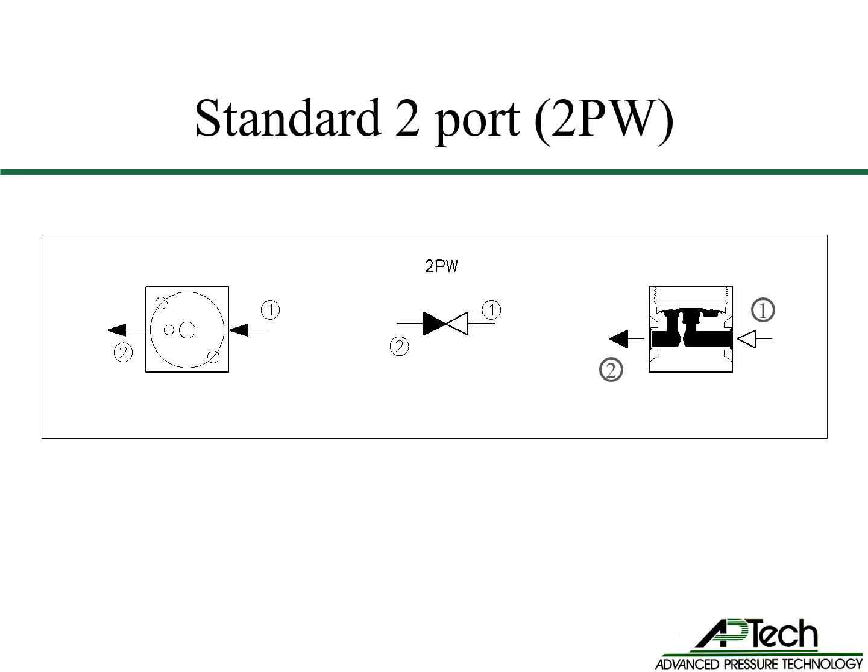These are three images, each showing the same 2PW valve with the same porting. The plan view on the left is a view from the top of the valve looking from the actuator side. The gas enters from the inlet, port 1, and exits through the outlet, port 2. The center circle is the seat cavity. The smaller circle to the left is the outlet port.